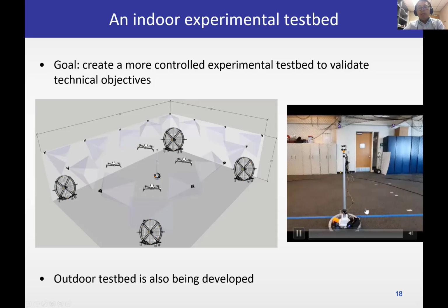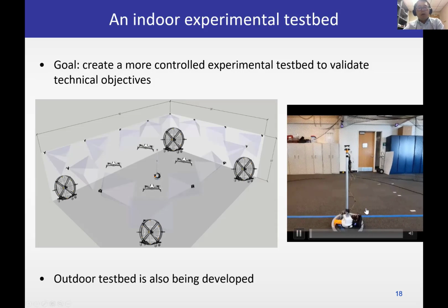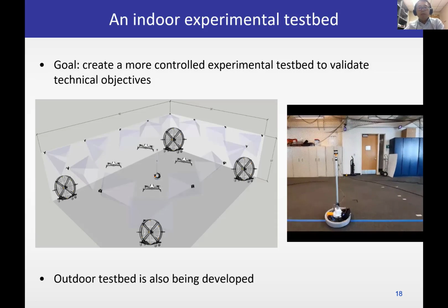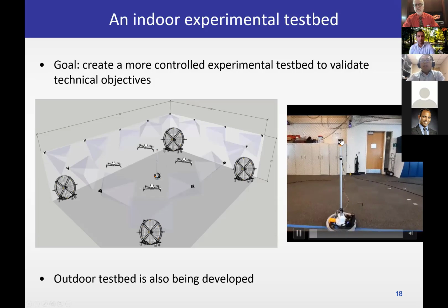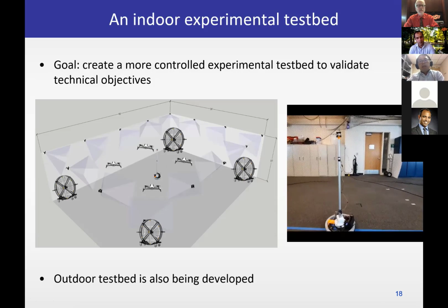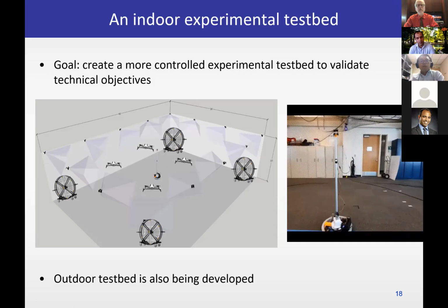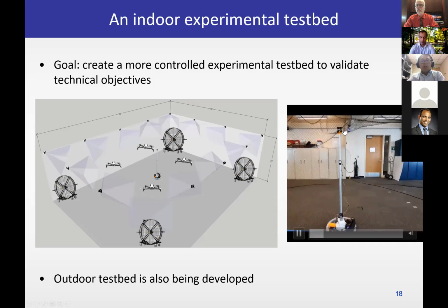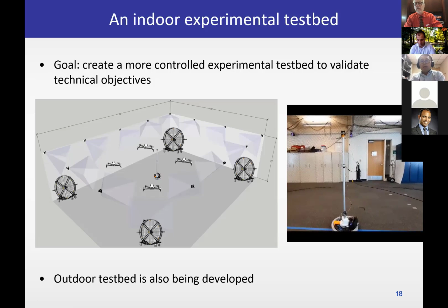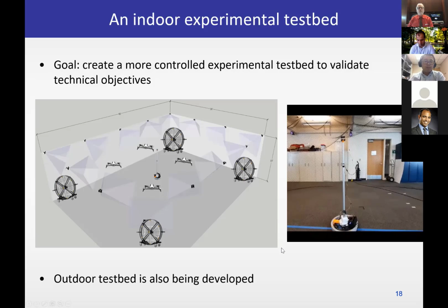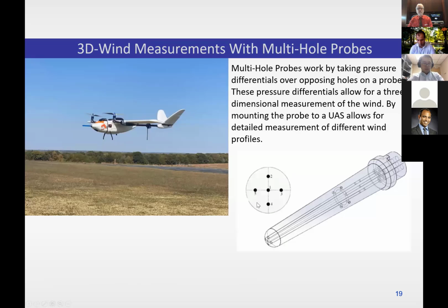So we developed this robot, which is controlled in ROS and through the motion capture system. There's a linear actuator that goes up and down to the desired height you want. On top of that, you can see there's a wind sensor that collects wind measurements. We're going to use that as the ground truth. Of course, we can switch that out with other wind sensors if they provide better accuracy or better measurement, so that we don't have to manually move it around to get the truth.